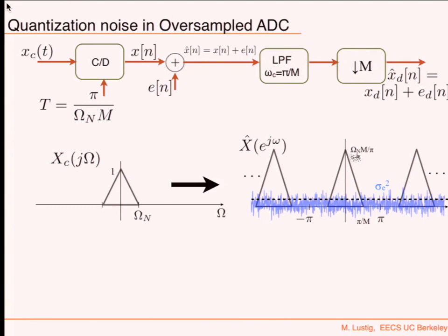What about the peak of the signal? It depends on something. Right? It depends on m. So for higher sampling rate, this will go up. What about the bandwidth of the signal, the digitized signal? What's going to happen to that? It's going to narrow down. Right? What about the energy of the entire signal? Is it going to change? Parseval.